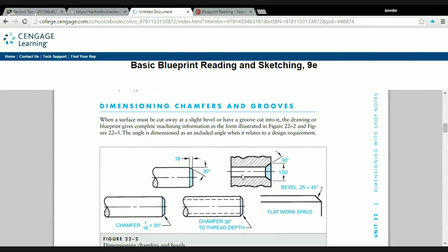And on the opposite end, internally here, we've talked about these before. They had a different name. They were countersinks. It's very similar to a countersink if you look at the chamfer here, dimensioned slightly differently, but same basic idea. It's basically to bury something down into the part. We've talked about it before, like the head of a bolt, to make it flush with the outer surface that it's going into. But chamfers can be used in that same way. Countersink and chamfer for an internal feature are kind of interchangeable as far as the terminology goes, used for basically the same purpose.